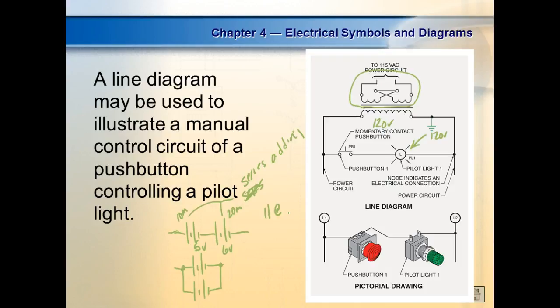No way, right? This one can only put out 10, it cannot put out 30. This one can only put out 20, it cannot put out 30. So the best we can do out of this is 10 milliamps. In a series circuit, current is the same through everything in the circuit. So here it would be your worst case. Whichever battery had the worst case, that's what the circuit would be rated at. So what you get is you add the voltage together. Okay, y'all understand? Yes or no?